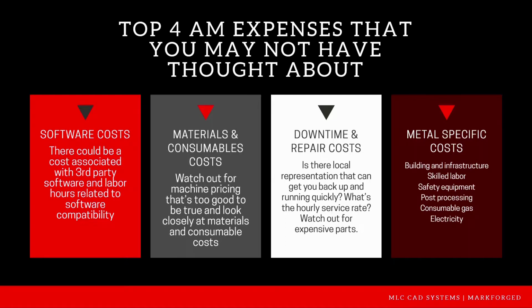Consumable gas, post-processing. So it's not 100% required with Markforged additive, whereas you will find with the traditional metal 3D printing technologies that have been around a long time, it's non-negotiable. You have to post-process everything. Oftentimes it's like welded or completely attached to the build plate, so you've got to remove all that. We actually have like breakaway supports for our metal. You may want to do a little bit of processes.